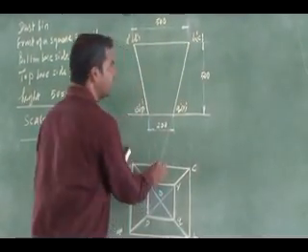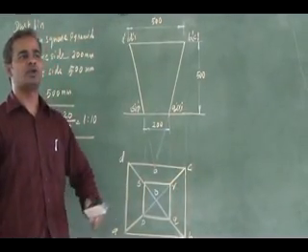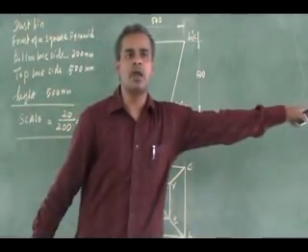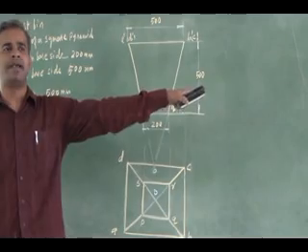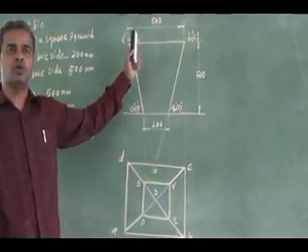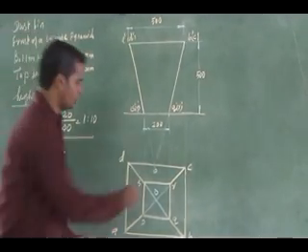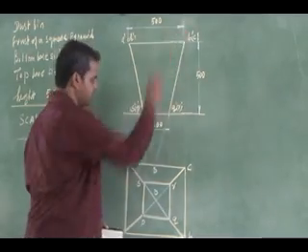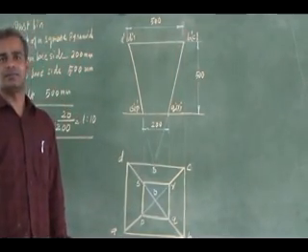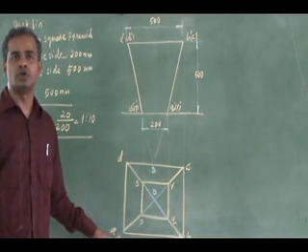From here, what I have to do is find the true slant length. It is a problem similar to your previous pentagonal pyramid in a tilted orientation. In the up and down orientation, what I have to do to get the true slant length: from the apex, I have to get the true slant length. Any one slant edge in your top view, you try to rotate.